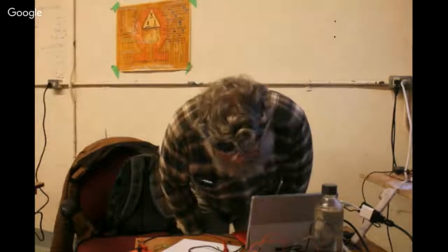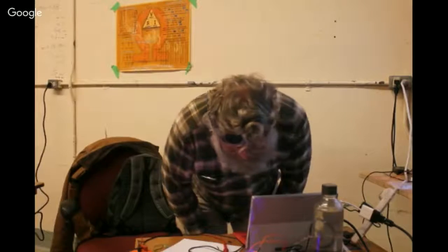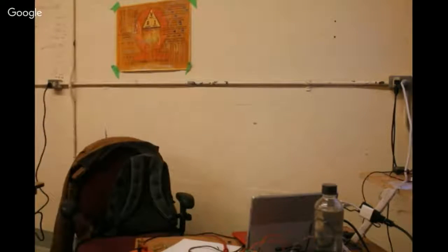One of the easiest is just to hold the iron to the wire, and then when the wire gets hot enough, touch a piece of solder onto it, with the iron still there. And yeah, so I usually actually just touch the solder to the very tip of the iron, and I let it melt down to the wire.